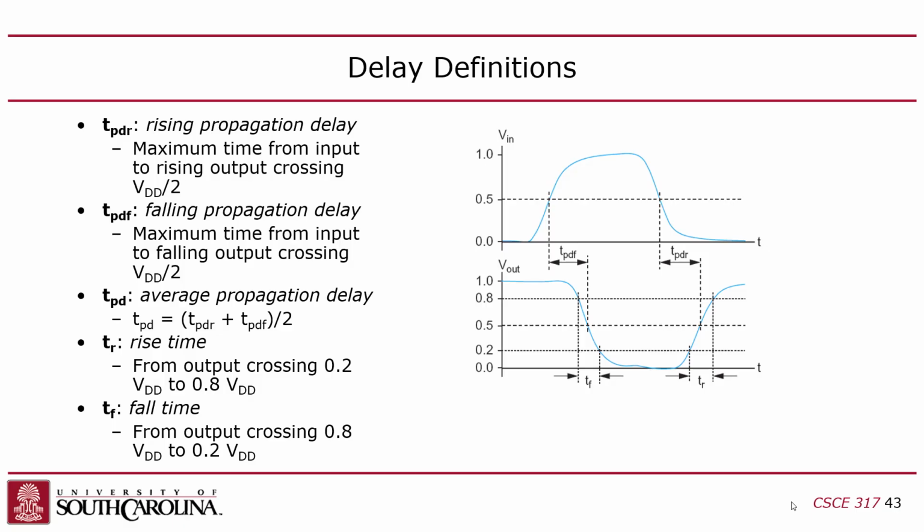Well, so basically, in this case, we split it out to rising propagation delay. When you have a gate and the gate input goes from 0 to 1 and the output changes from 1 to 0, the propagation delay, like we didn't differentiate this in the previous lecture, but there's a rising delay, and this is measured generally from halfway.